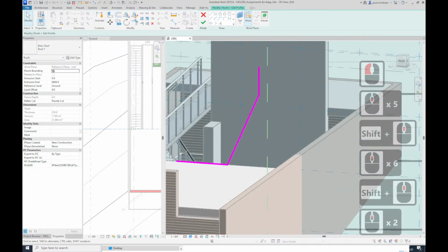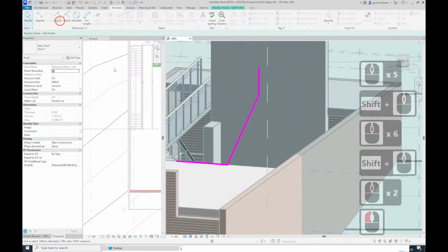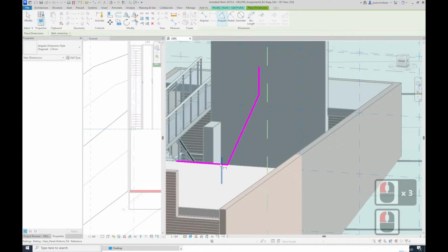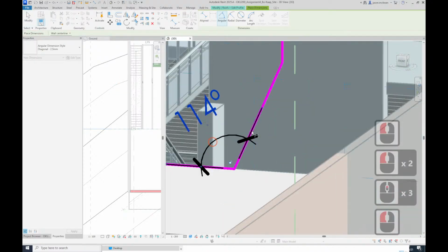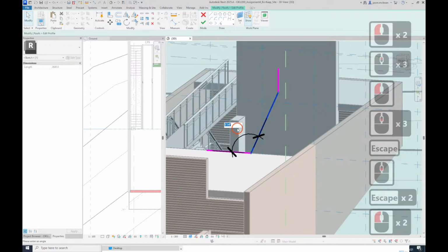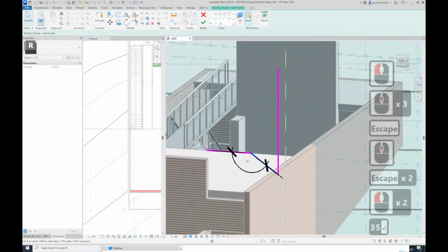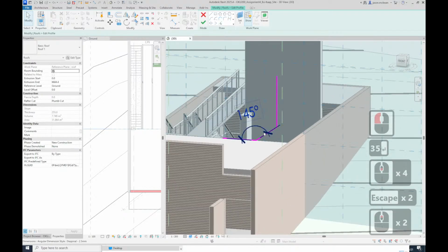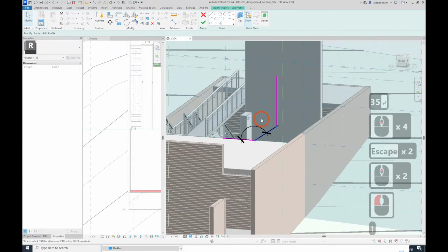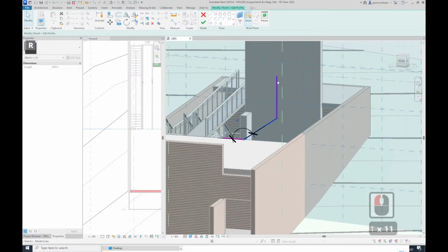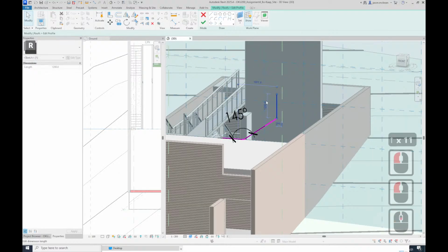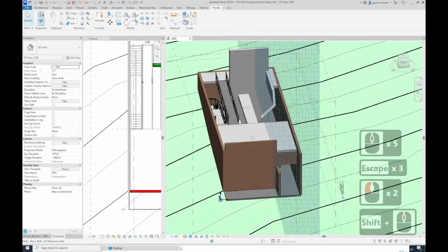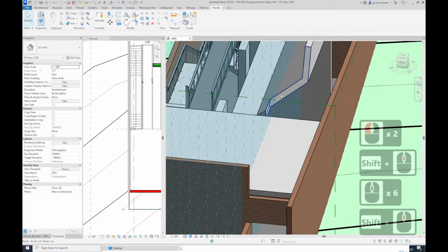So now if you go to Annotate, you can use dimensions. Come on, angle. You can keep these dimensions in here. So now you can say 35, minus 35, sorry. 35. So now you can be quite deliberate of how much you want to cut and how high this wants to be. See that? So the whole time I'm changing, but now this just needs to cut a bit more.